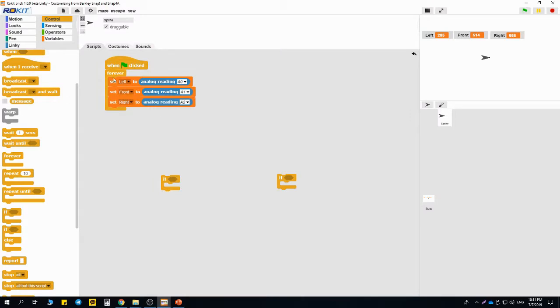Let me check here our sensor. Okay, when we go forward, and if our left side detects some obstacle from the left, like this, okay, so it means that our car should turn to the right side, because in the right side we don't have anything, we don't have obstacles. So let me show how we can make this code.